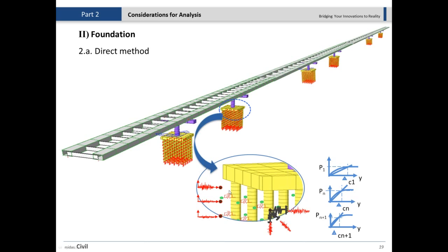All right, one more thing. So far we talked about simulating the springs. But it's very important to consider that the springs just represent the nonlinear behavior of the soil and the structure. Depending on the depth and the location of the piles, those nodes or that part of the pile may also experience different forcing functions.